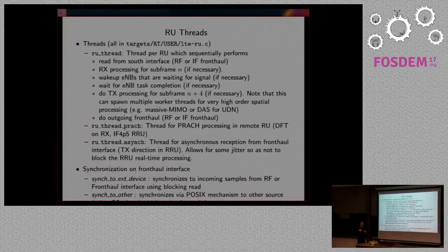So there's a dependence between the signal you transmit in the future and the one you're receiving at time n. So the way we decided to implement this was that fundamental thing in LTE, it's at time n plus 4 milliseconds. So the signal you receive at time n is necessary to generate the signal that you transmit at time n plus 4 milliseconds. That's the way it works.